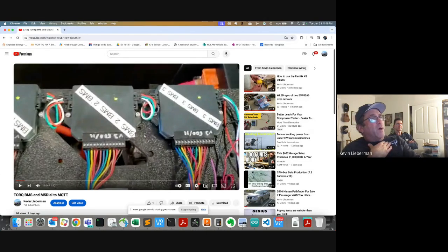So anything that's above that 4.15 set voltage, or whatever I decided, it'll put a resistor across that battery cell in order to get that voltage down. It's a very, very small resistor, but over the course of a lot of time, it will bring that cell down to that voltage.